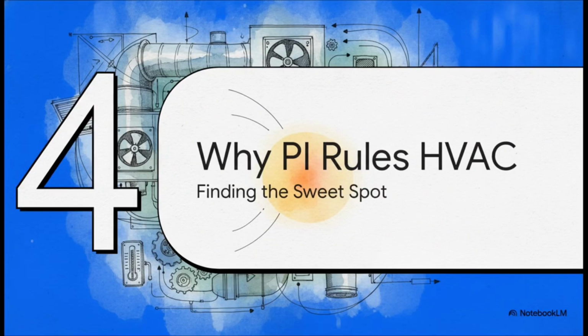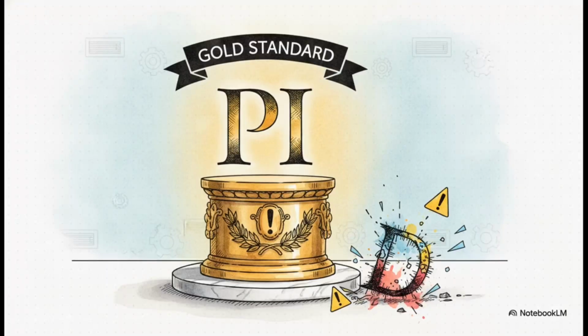Section 4, Why PI rules HVAC, finding the sweet spot. Now on paper, full PID control sounds absolutely flawless. But here's the thing, in the HVAC world, we rarely actually use the D. We almost always just use PI control.